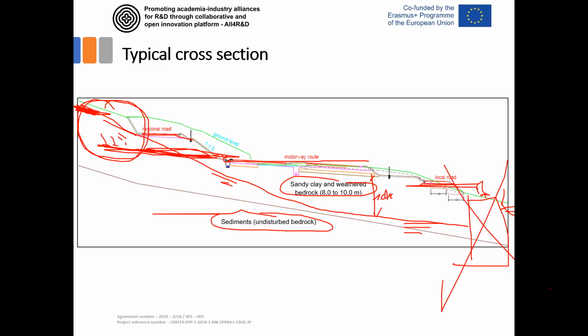However, the monitoring is performed. Now it will continue to be performed every 3 months or every half a year, just to get an indication if some problem is about to occur. What is very important is the diagram of the time versus lateral displacement. If this diagram looks like this and it's all the time the same increment, then it's not indicating some problems.